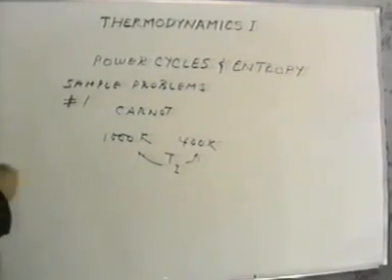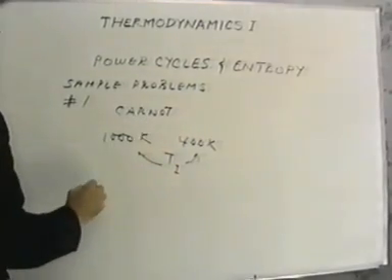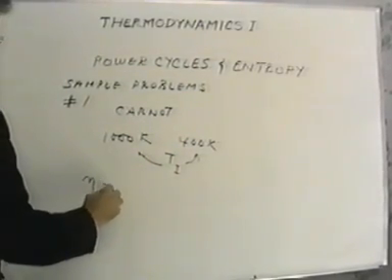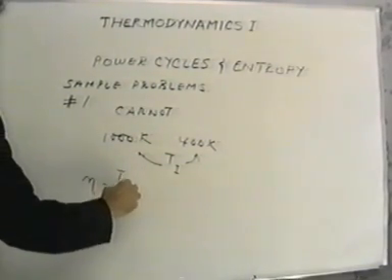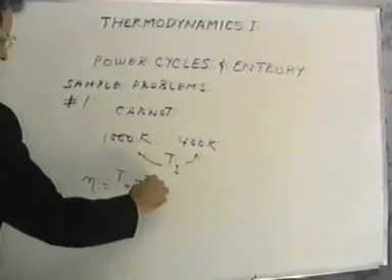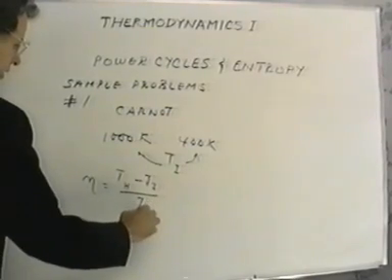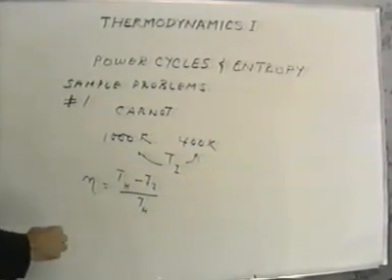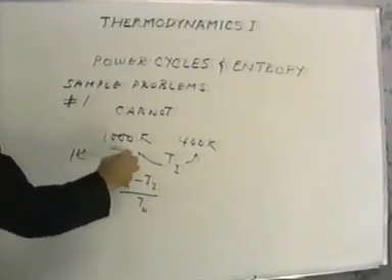Now we start off by defining what we mean by a Carnot cycle. A Carnot cycle has an efficiency which is quite high, and this efficiency is given by the difference between the high temperature, and in our case the intermediate temperature, T sub I, divided by T sub H. Now this would be for the first engine, the one that's at the higher temperature.